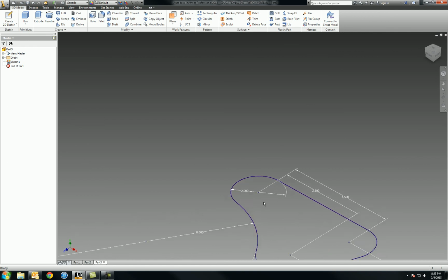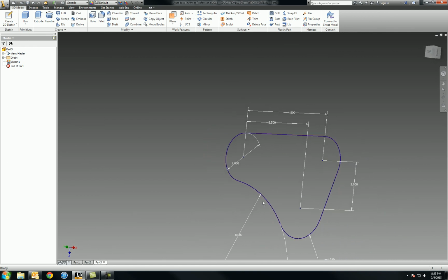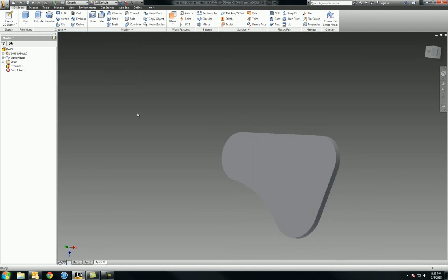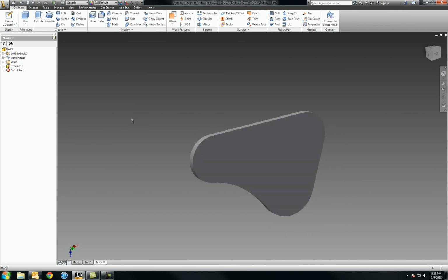And now I'm going to extrude this sketch. So I extrude it, and it has a thickness of 0.25. Now that I have this in place, the only thing left to do is to place my holes, and all the holes are concentric in this particular object.